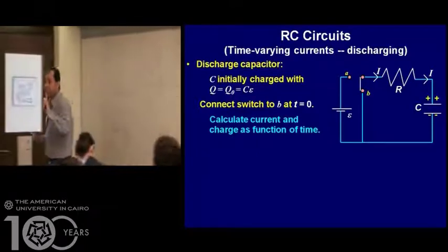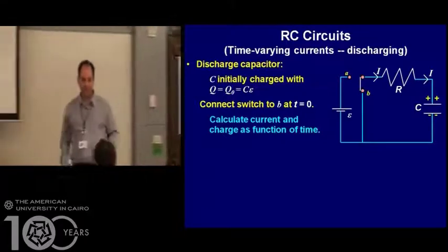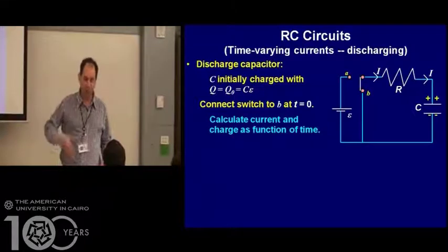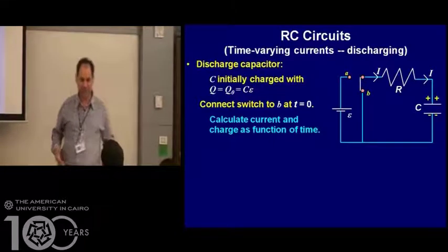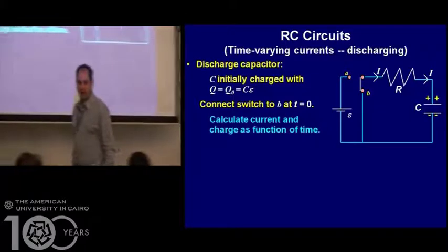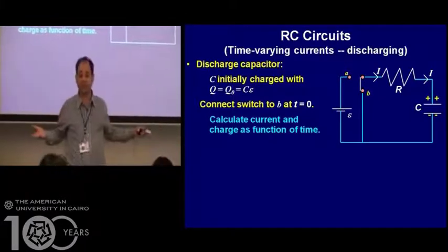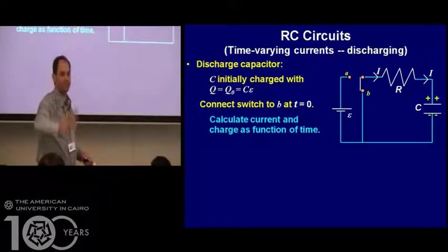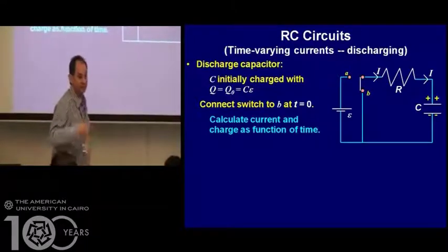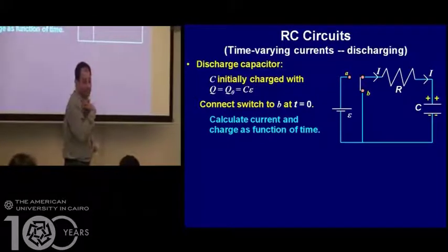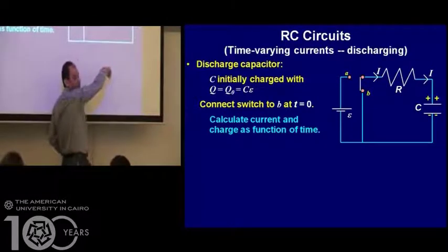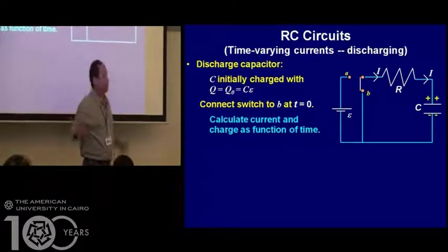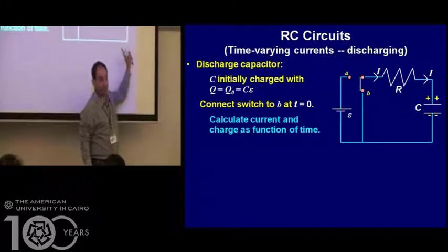That's a very good question. Can you answer it to me after I get the other part of the circuit, when we are charging the capacitor? Why do we get negative current? What does the negative current mean, guys? It means that I have assumed that the current is flowing in that direction, but from my solution, the current actually is flowing in the other direction, and it makes sense. If this is the battery, the current should flow in the other direction.